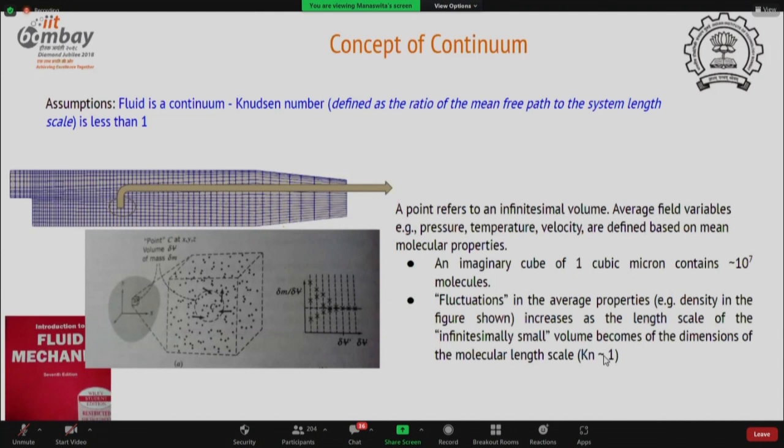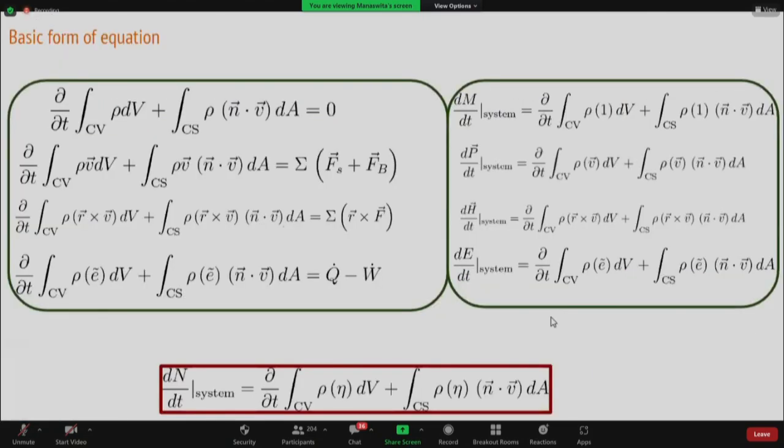Now, when we have established fluid is a continuum, the other thing we have to do is write down the mass and momentum conservation equation for fluid. Mass and momentum conservation equations we have been writing for ages for a system, like dm/dt of system is 0. This is the total derivative, the ordinary derivative. This says that mass cannot be created or destroyed.